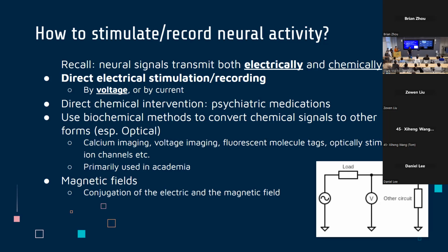Okay, so can anyone tell me how you use a voltmeter to measure voltage? To measure voltage, you measure 2 points. Okay, so if you connect 2 points, what are you measuring? The difference. The difference? Okay. So say I want to measure the voltage at this node. The example here is showing that I'm using a voltmeter to plug one end to that node and the other end to ground, so that I can know, okay, this is the voltage of this node.